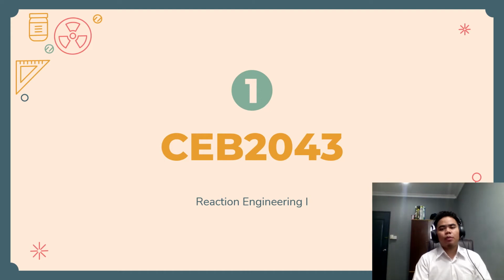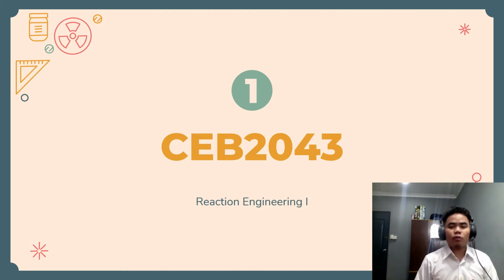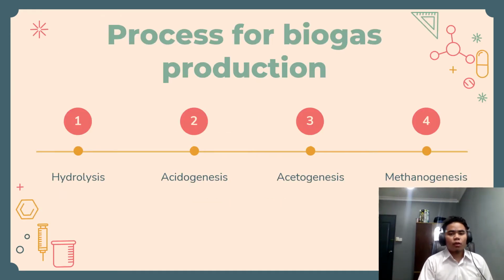The purpose of this paper was to give a review and evaluate recent studies in the field of producing biogas by determining the critical parameters and their impacts on the anaerobic digestion process. We studied most of the articles and found that there are four major reactions that occur for producing biogas: first hydrolysis, second acidogenesis, third acetogenesis, and the last one methanogenesis.